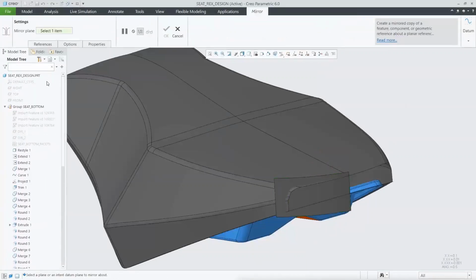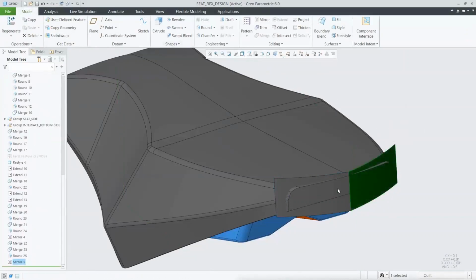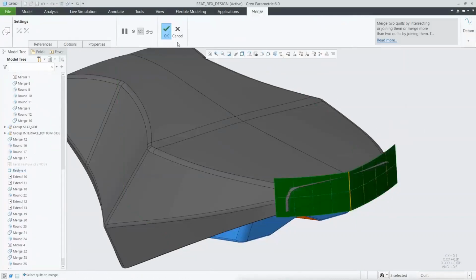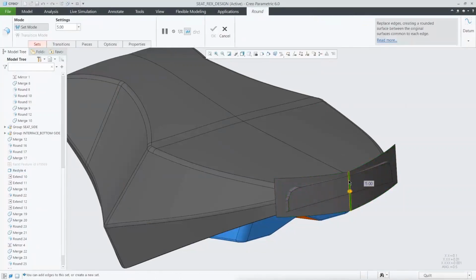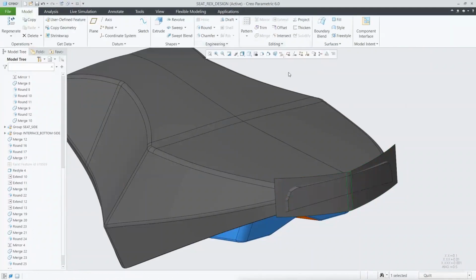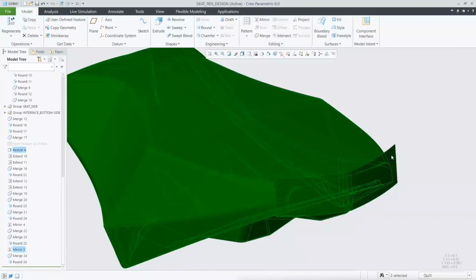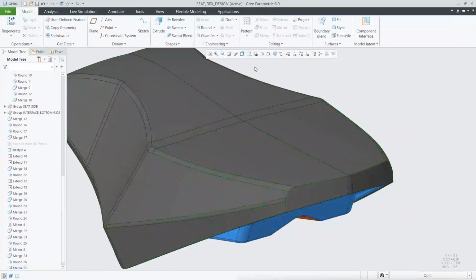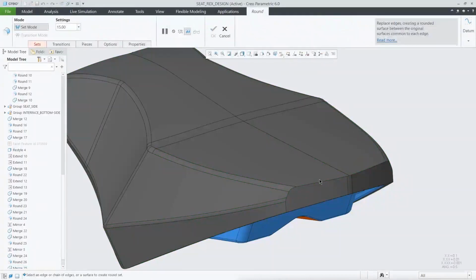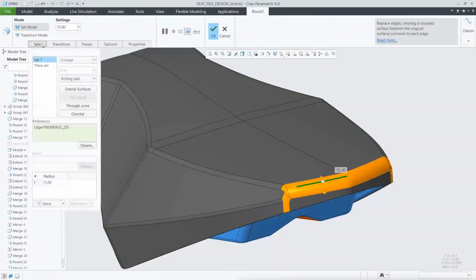And again, the surface in the back, you can do any of that work in sequence, or if it's later on in the process and there's even something you forgot, like I mentioned, you can go back and still do your merging, do your rounding, do your different Boolean operations that you might need to get to the final surface that you're looking to take forward and work with from that point here. Let's go ahead and merge those in. Round off our final area here.